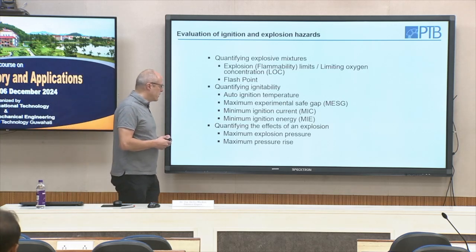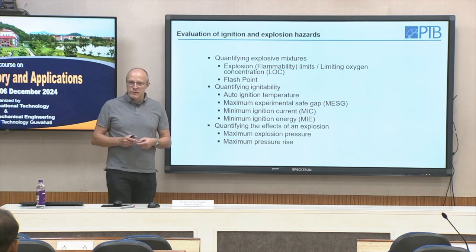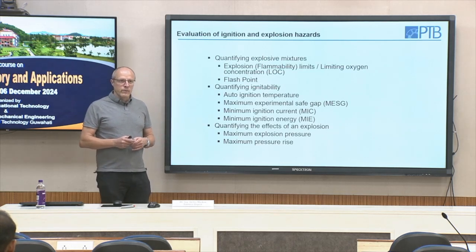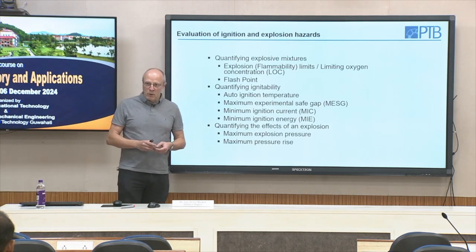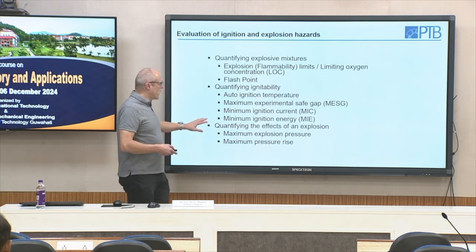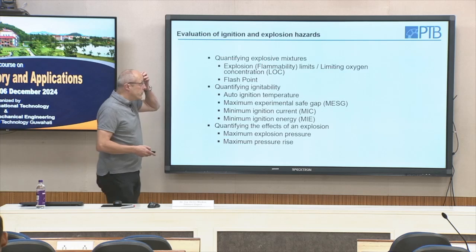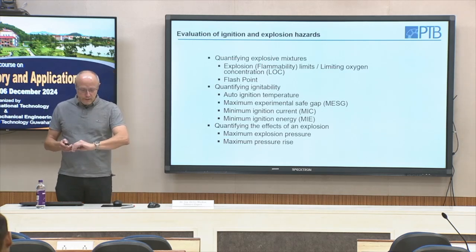And if you know that the measures you have taken for other combustibles in the same group are valid, you can use these measures also in this gas group, explosion group, for other combustibles. So that's the idea. And we have again these 3 main categories, and now we will go into some details here.